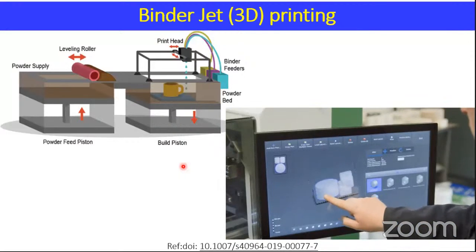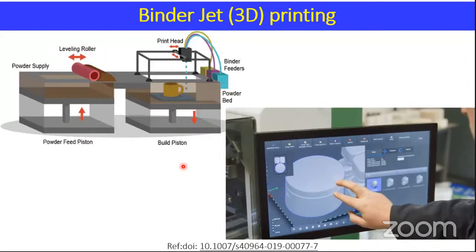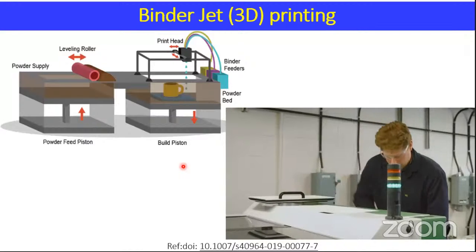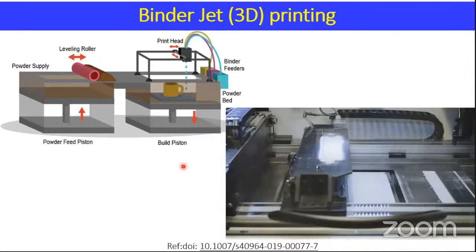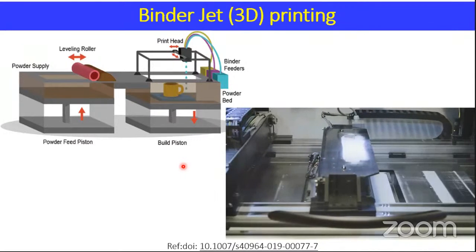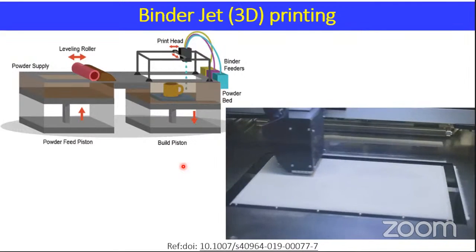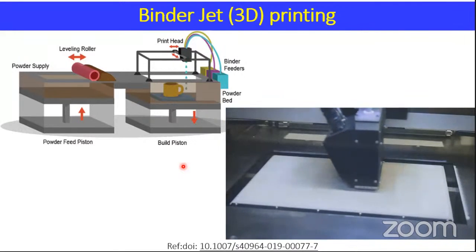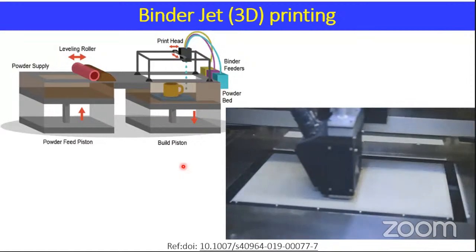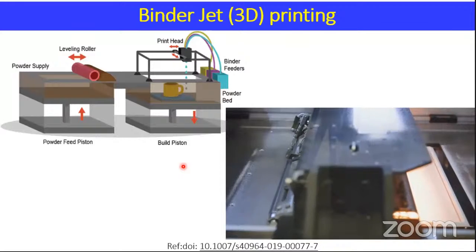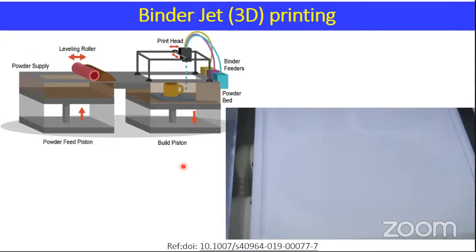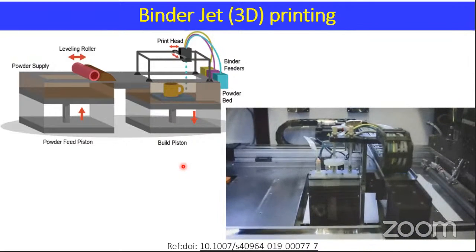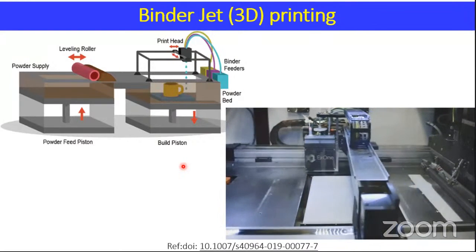To start the process, a 3D drawing is imported into the printer software. The powder to be used is placed in a dispenser, which ensures a constant supply during printing. First, a powder layer of a specific thickness is spread. Thereafter, the printing head, moving on 2 axes, projects the binder where necessary. Before moving on to the next layer, the solvent contained in the binder is evaporated by an incandescent lamp. The powder bed is then lowered and a new powder layer is deposited. Therefore, the production takes place in a series of steps that build the part layer by layer.